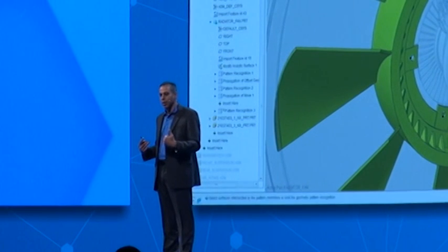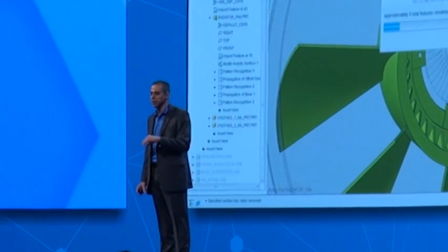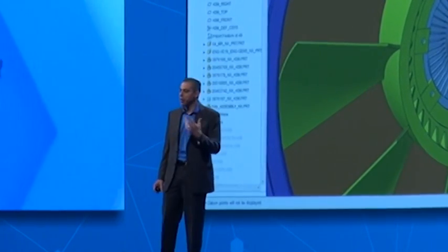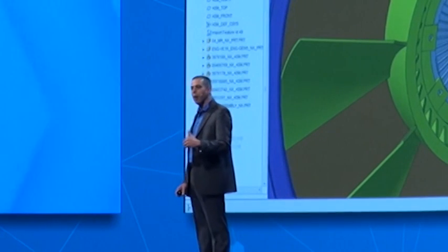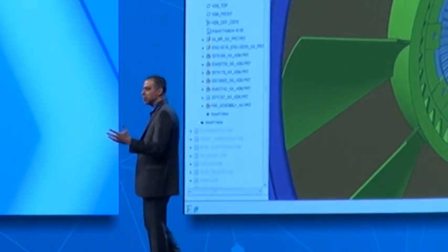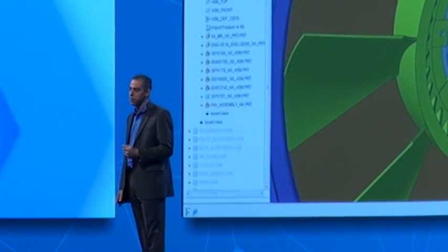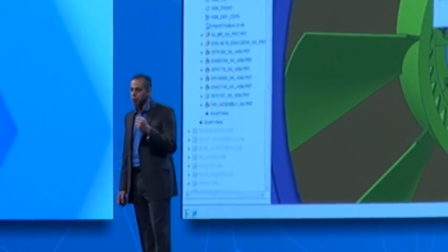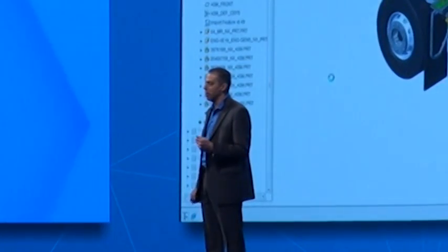Okay, of course, if I've changed the number of fan blades and the diameter of the fans, I'm going to pull more air through, and I'm going to change the number of mounting elements to mount this fan blade to the assembly. And then I'll use some brand new technology from our partners at B&W that's integrated into Creo Parametric 3.0 to use standard fasteners to just assemble that fan blade to the assembly. All right, so that's consolidation with PTC Creo 3.0 and Unite technology.